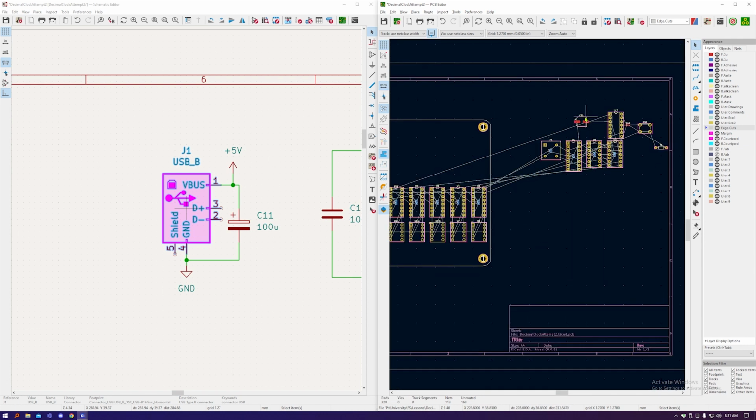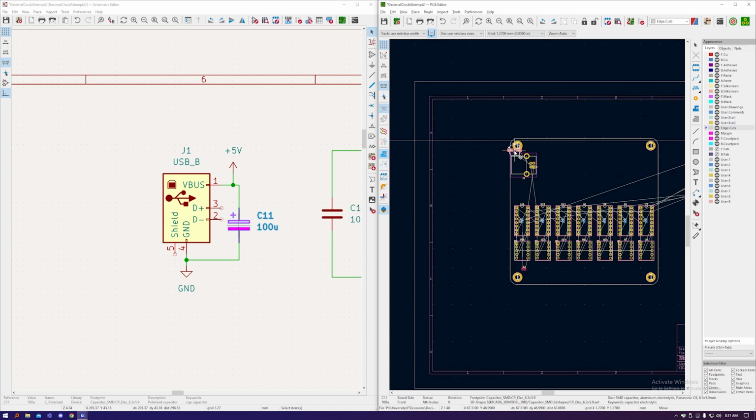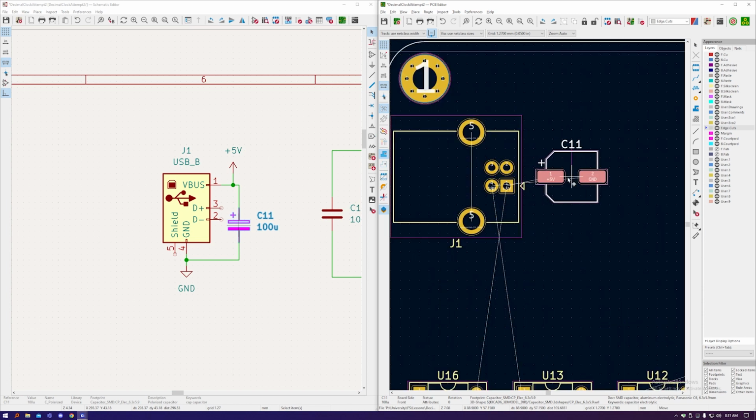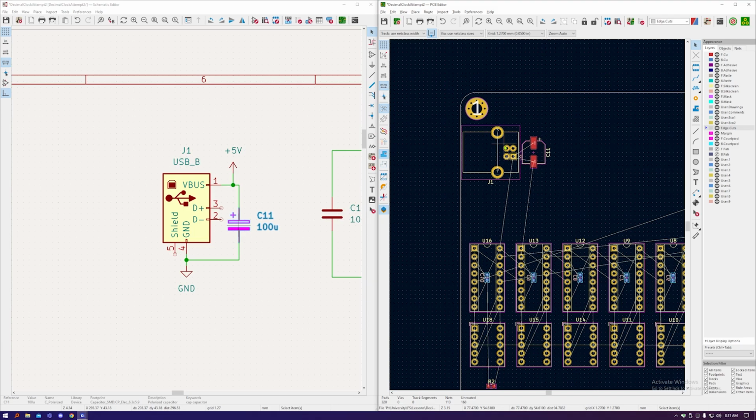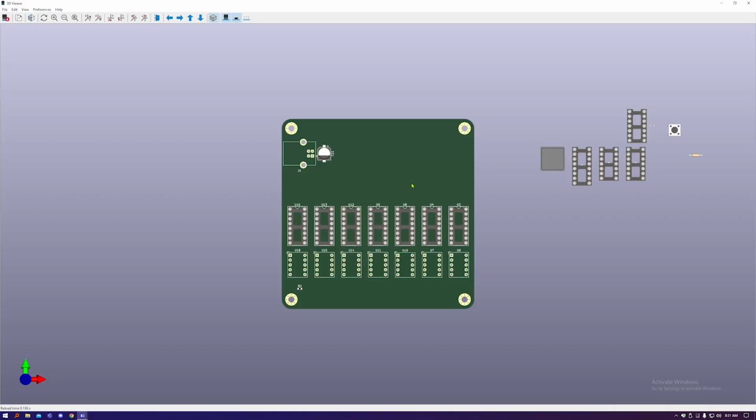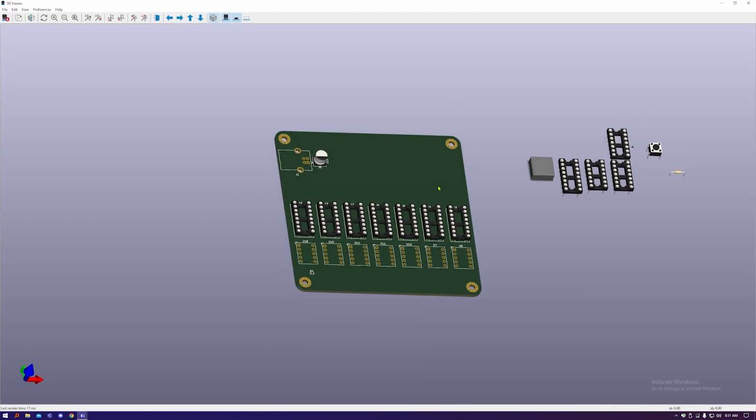And we also want the fat decoupling capacitor C11 to be close to it. So I'm going to rotate that like so, and that's just going to sit there. And again, we can check in the 3D viewer to make sure it all aligns how we want.